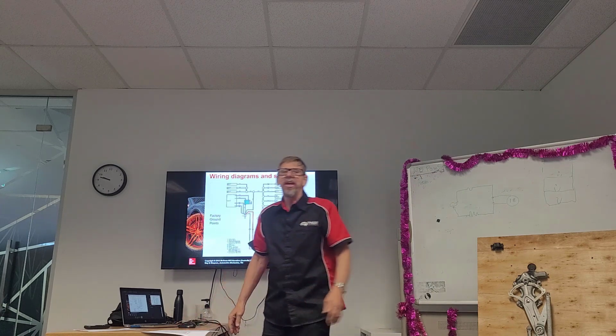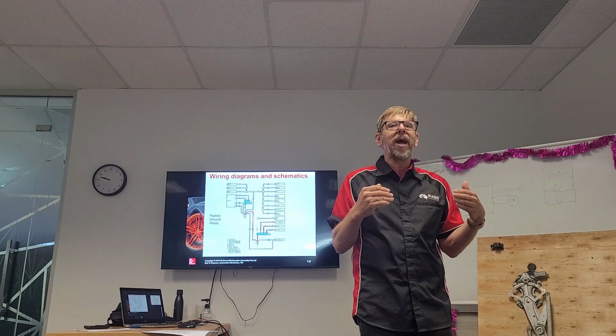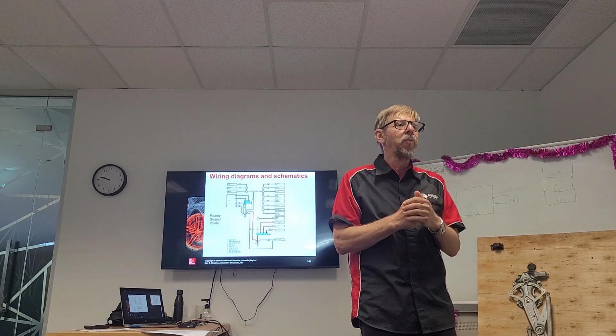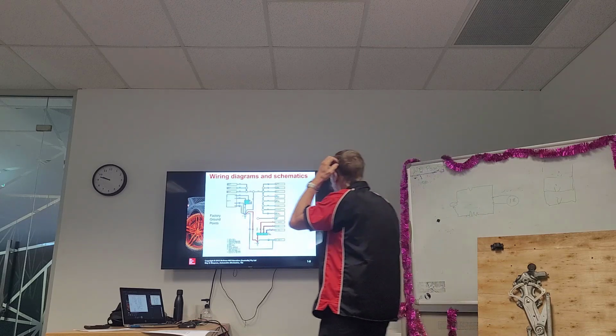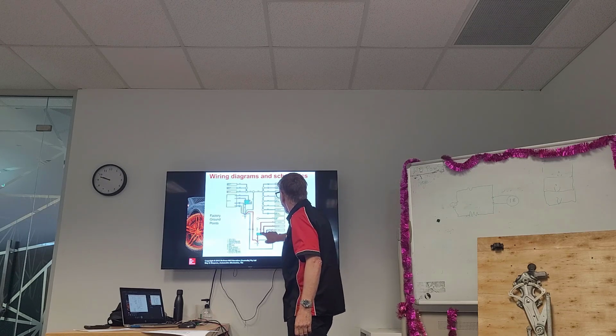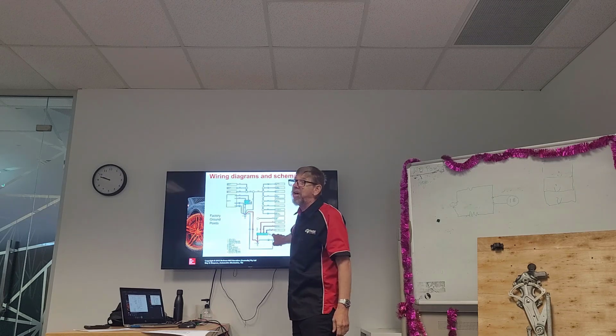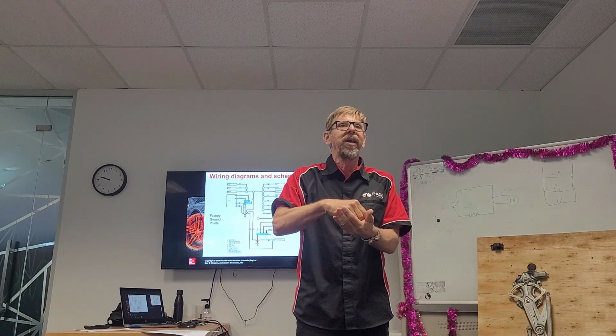Okay, the other thing on wiring diagrams, we've got workshop manuals to locate grounds. Sometimes we want to know where our grounds are, we don't know where they are, but this is out of the wiring diagram, and it's showing you the different components that are grounded through a junction box. A junction box is where all the terminals come to one point, okay?